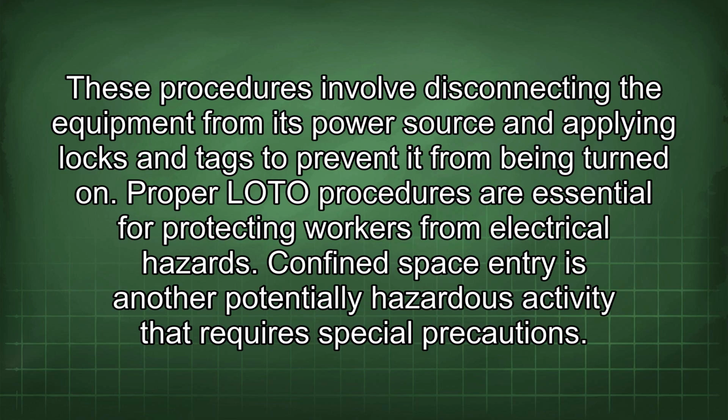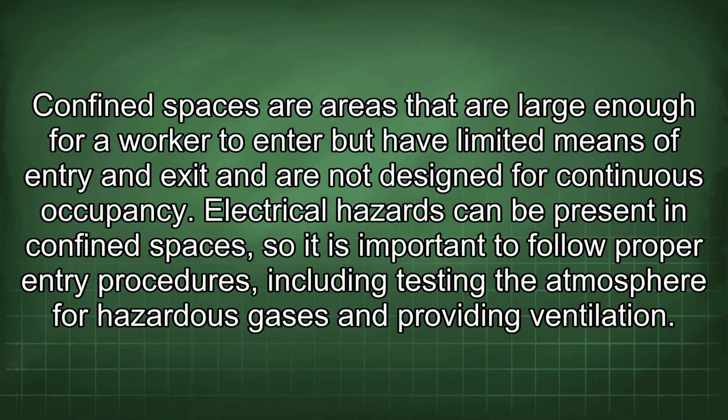Confined space entry is another potentially hazardous activity that requires special precautions. Confined spaces are areas that are large enough for a worker to enter, but have limited means of entry and exit and are not designed for continuous occupancy. Electrical hazards can be present in confined spaces, so it is important to follow proper entry procedures, including testing the atmosphere for hazardous gases and providing ventilation.